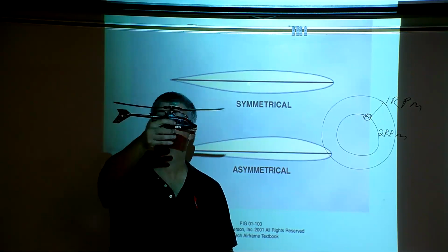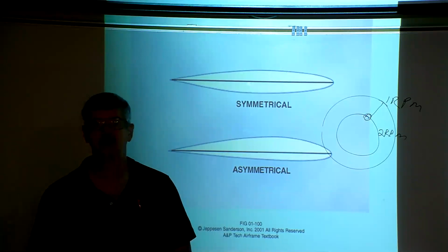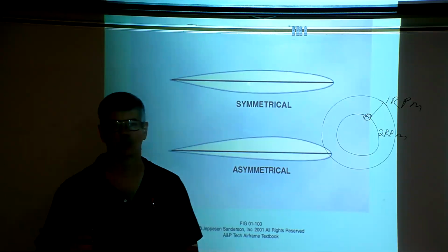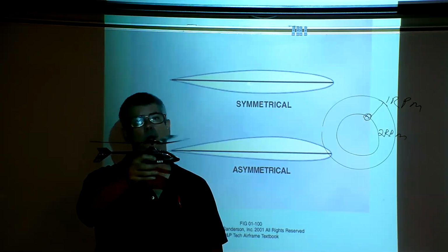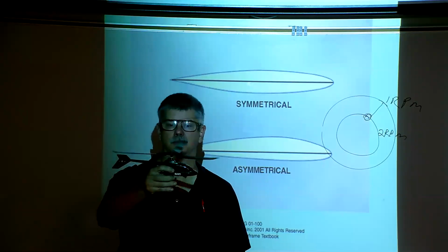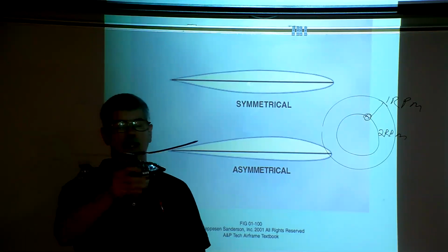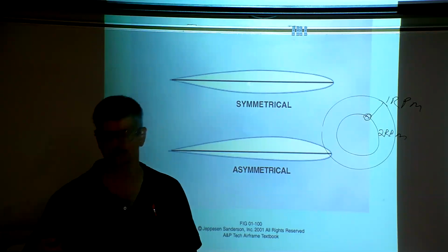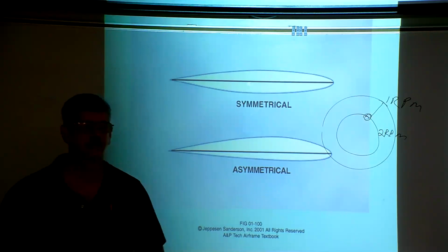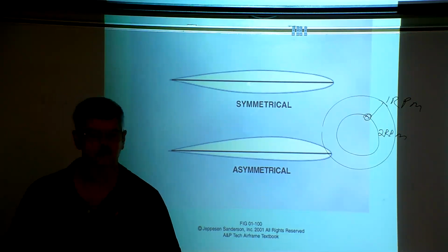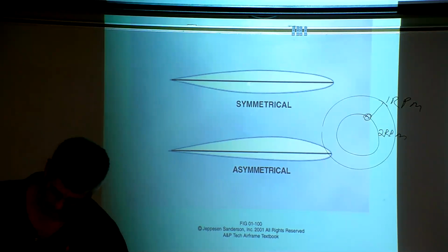As we go up to about 18,000 feet, the density of air is about 1/2 of what it is at sea level. So at 18,000 feet, the helicopter would now have to push down 2,000 units of air, because each unit of air only weighs 1/2 pound. And so we end up getting into limits of how much volume of air we can push down, and thus only a certain height would we be able to fly. That was density altitude.